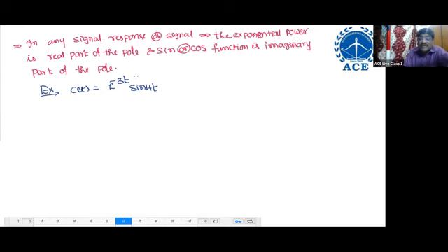Because even if you integrate 1000 times, e power minus 3t will become e power minus 3 only. It won't become 4 here. Sine becomes cos, cos becomes sine, but this 4 never changes. It won't become 5. That means pole locations are never going to change. That's why, blindly, you represent a pole: this is minus 3, the real part of the pole.